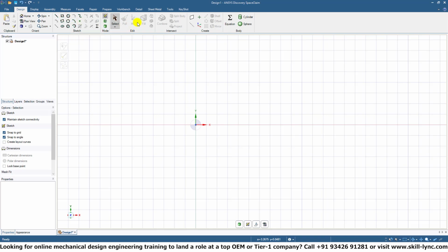If you use some of these more complex tools, you can get more complex geometry, but it becomes more tedious and requires more effort to get the program in line. You might get the program crashing on you, because the more features that you define, the more memory that's used up, and the more computational strain it puts on the program to remember all of these relationships and dimensions.